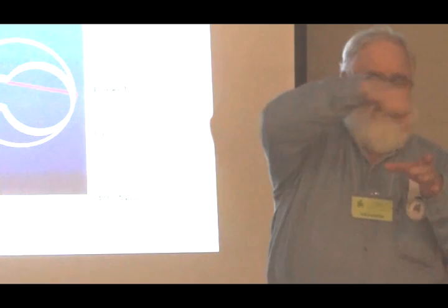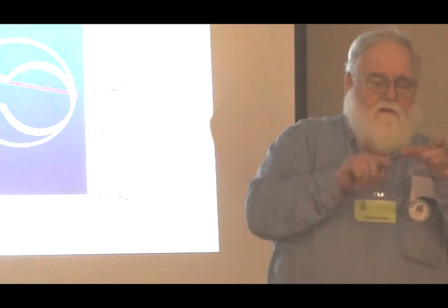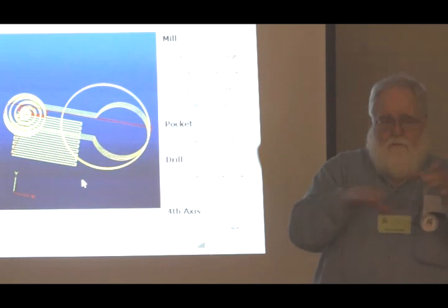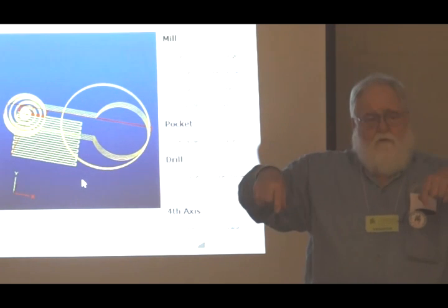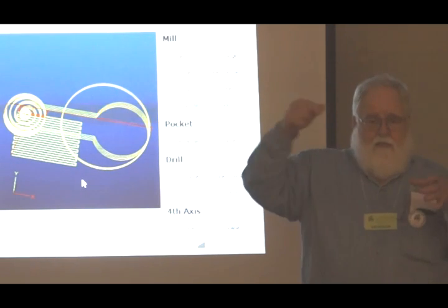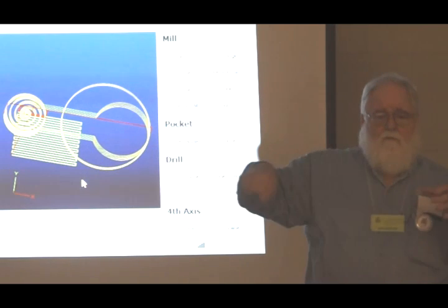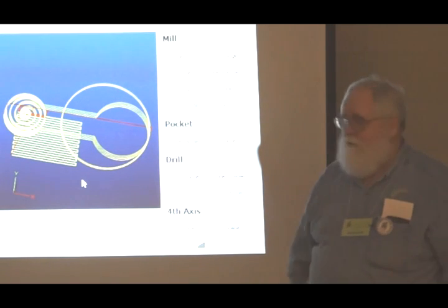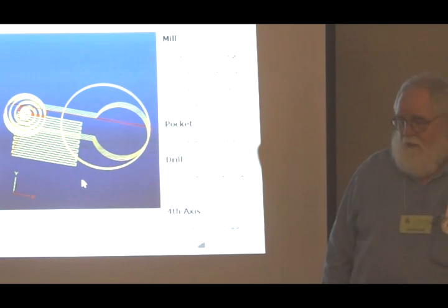Then I did a circle around each one of those towers down only to the level of the top of the link. So there were two circular operations. Then I did a link operation that went down and around the whole thing. I cut the whole part and I did the whole code in the Wizard. And of course I forgot to put it, this is a new laptop I bought just before this. I forgot to put the job file up here. But that was an example of making a fairly complex part by doing multiple operations.